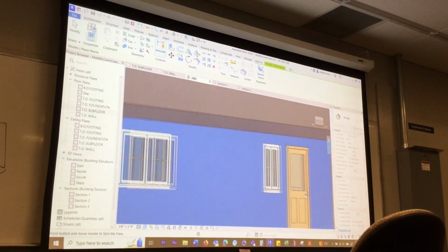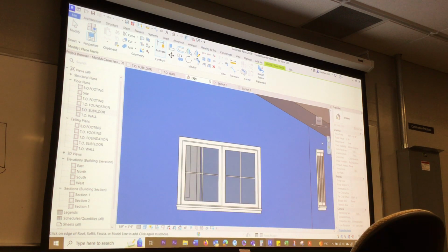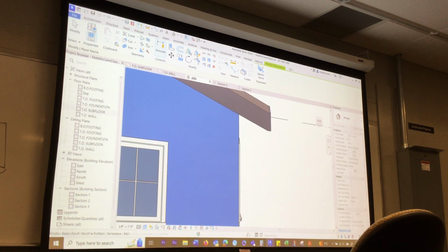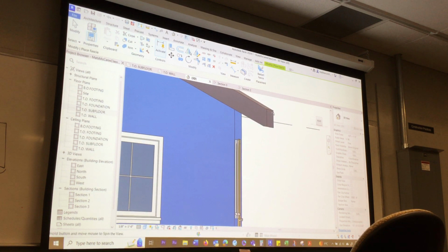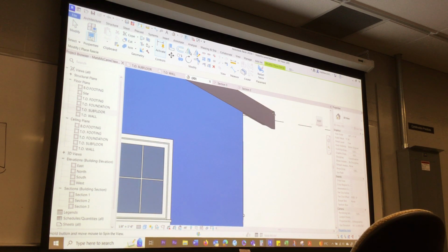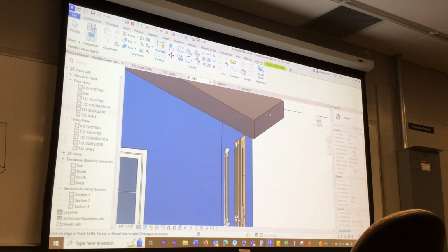If you zoom in here, it even finishes off this little tail. Anybody's ever built this stuff before, it's always a pain. You end up with this sharp little thing. It also doesn't draw correctly either because fascia doesn't go on this way. There's a way to smooth that out, but I'm not worried about it right now. The sheathing and everything should come over top. We're not really concerned about that. We're just making a correct model, right?